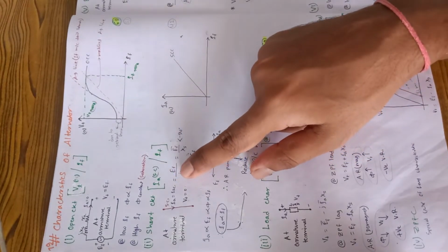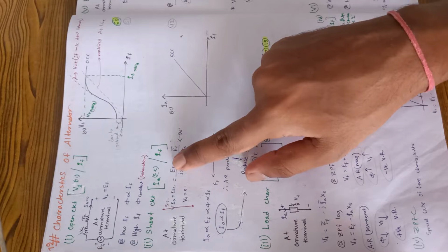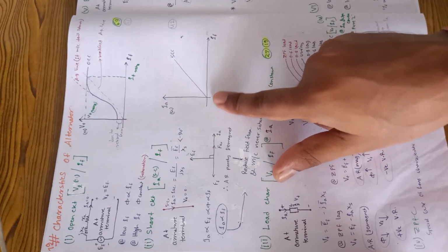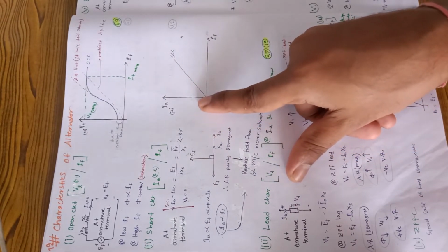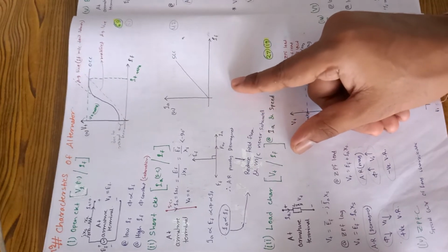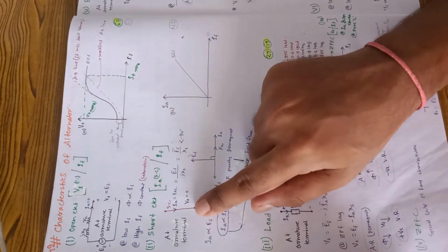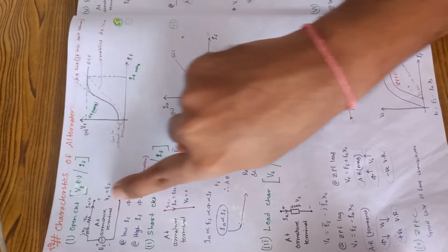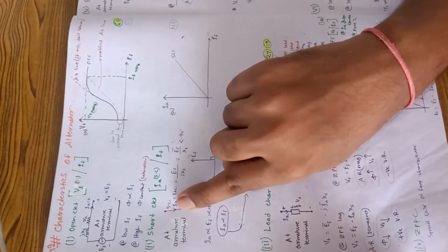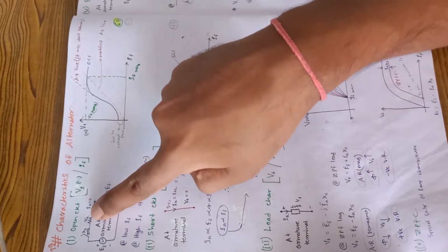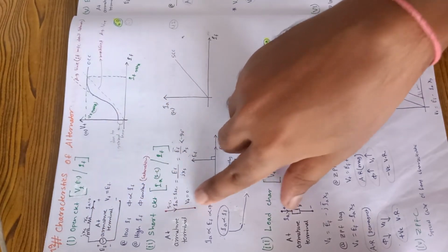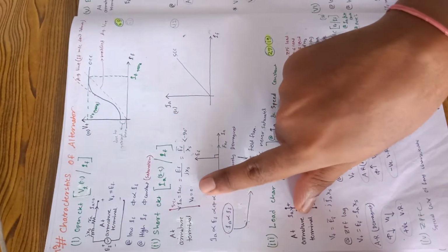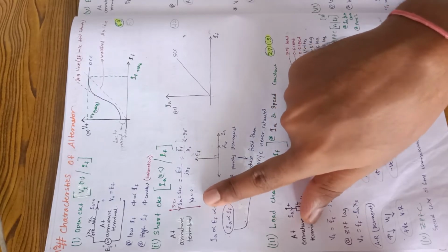When we talk about the short circuit characteristic, it is the characteristic between Ia and If. Ia, that is short circuit current, versus If. Open circuit was between Vt and If; here it is Ia and If. See, this is an equivalent circuit. What we will do here is just short circuit this terminal. When we short circuit this terminal, we generally neglect resistance, you know very well. We will consider only this one. And if we short circuit, then we only have the inductor. Due to this inductor, the armature current will be purely lagging.